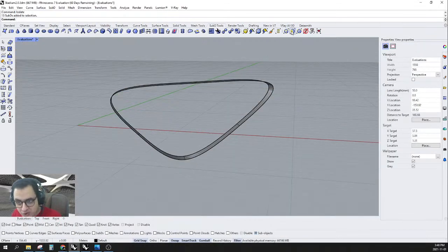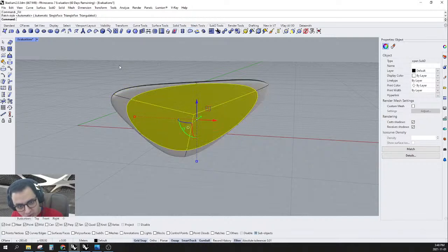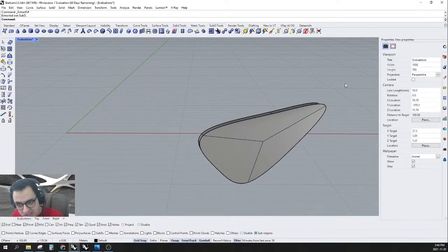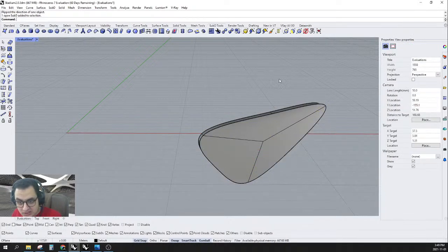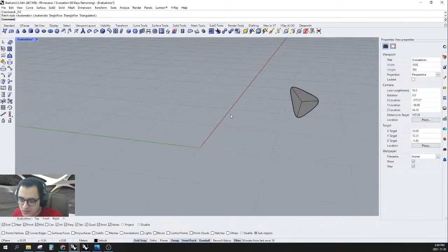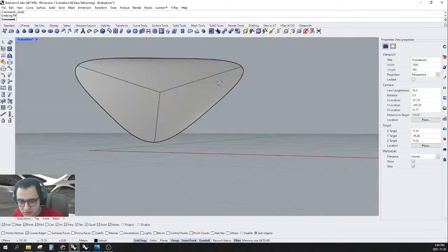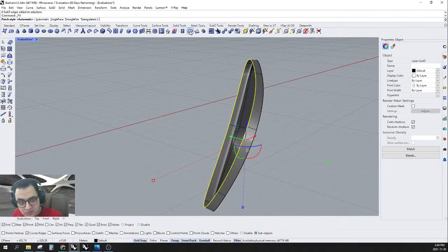And as we did before, we can select the curves right here, make a hole, sub the hole, okay, and extract it. And after that, go to none, select the one in the back, flip it, and select the curves again. Double click and select fill sub the hole. Okay, what happens? Select the curves again, fill sub the hole.